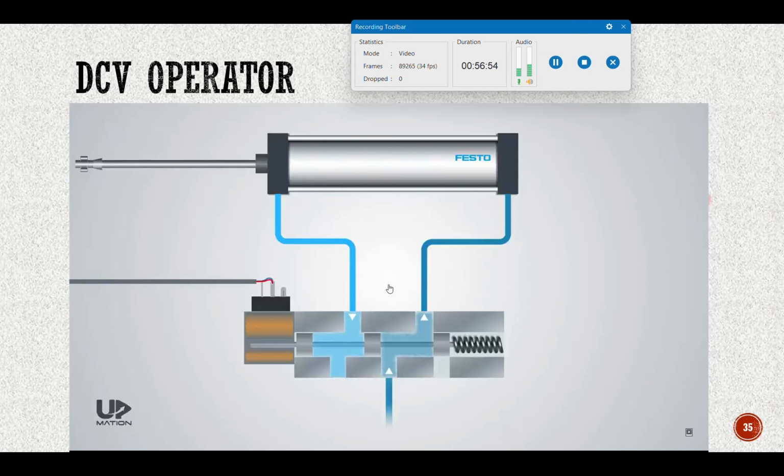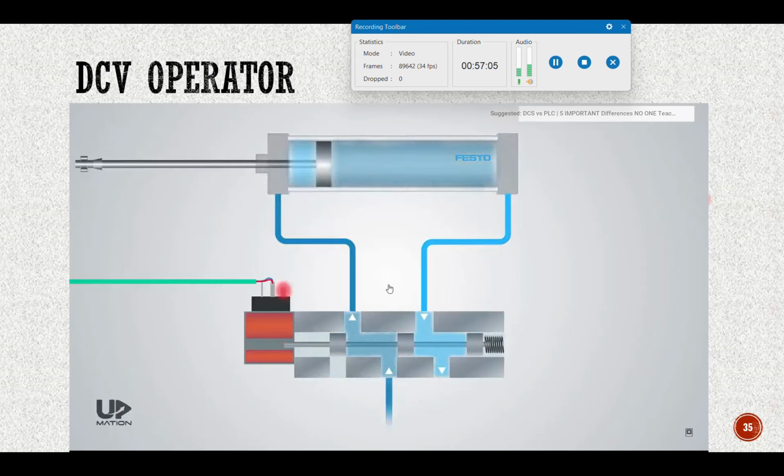As you may be familiar with solenoids, when it gets energized by a command from the PLC card, the coil will push the spool and thus squeeze the spring on the other side. As a result, you see the piston of the cylinder move to the right side.